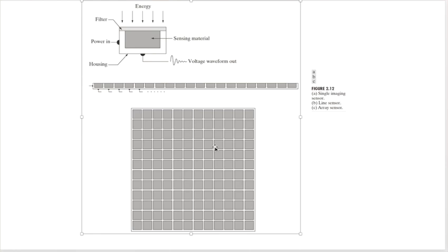So if you've ever had two friends take pictures on their phones, and one of them ends up looking kind of more greenish, and one looks a little more reddish, and you put the two pictures next to each other and they look really different, what you're seeing is the efficiency, how well did it filter out the light. Now, for your kind of pictures, we can tweak it afterwards, so we just say, who cares? Go with the cheap thing and away you go. Those lenses, the filters, are the expensive part. Really good filters are a lot of money, because you just have to improve that quantum efficiency.